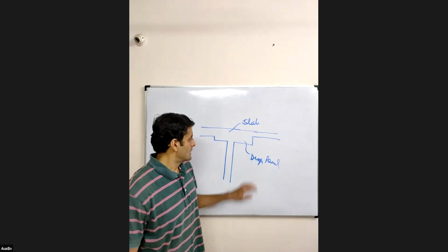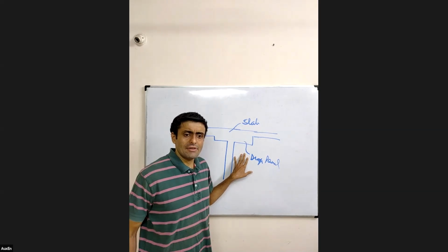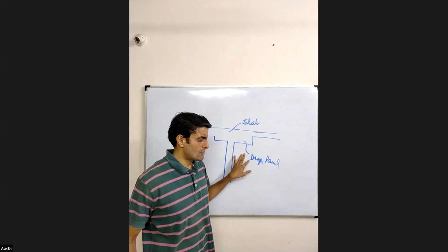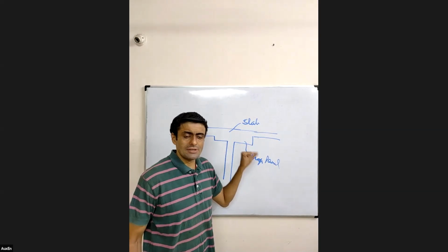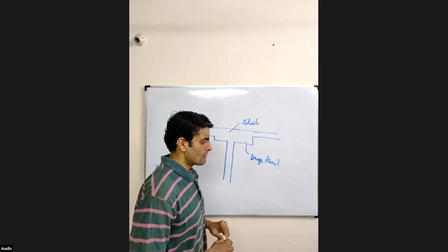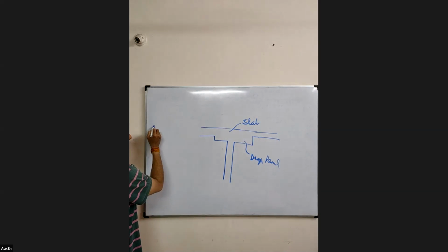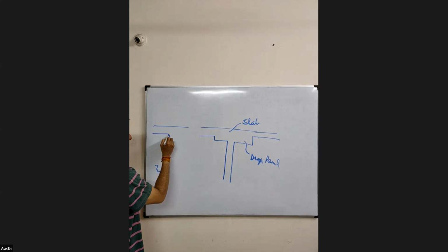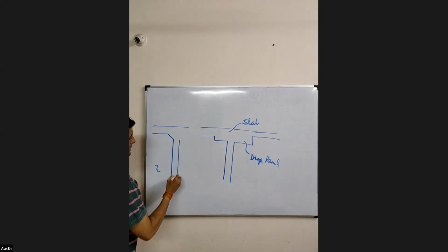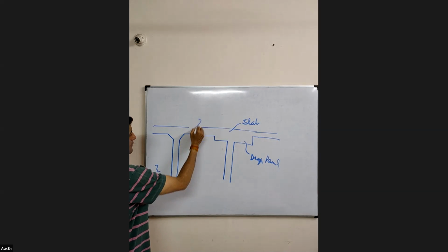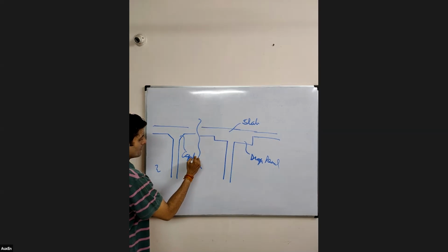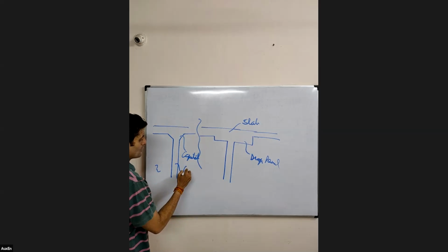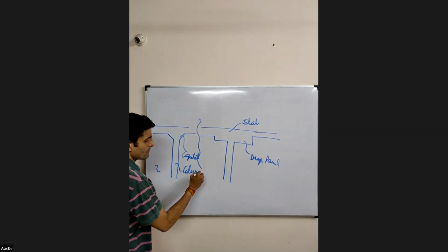Okay. So this is the second strategy we have, to provide drop panels where we are locally increasing the slab thickness. Okay. And the first strategy that we were talking about was to provide our column capital where we are locally increasing the column dimensions. So where do you see these column capitals being provided?